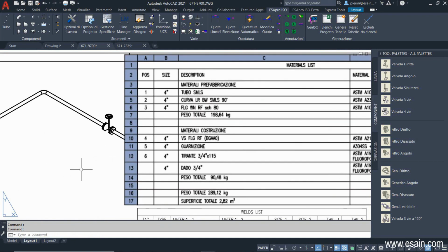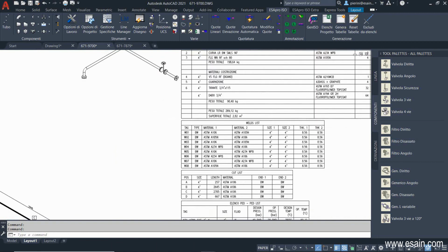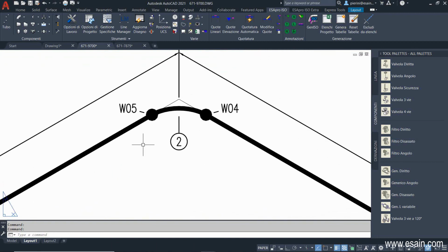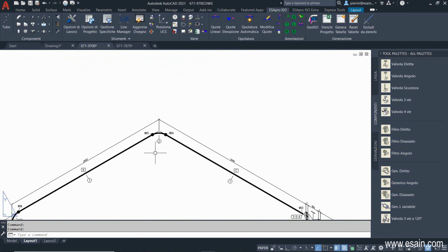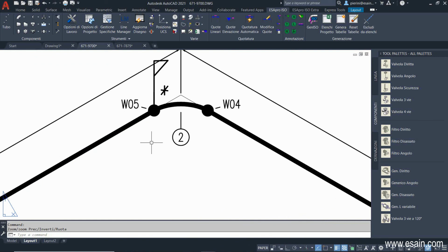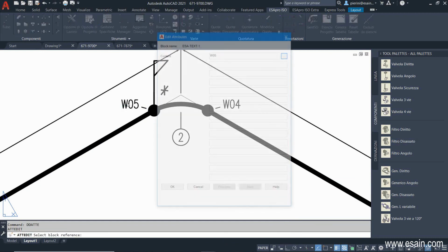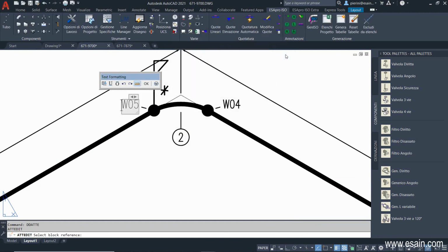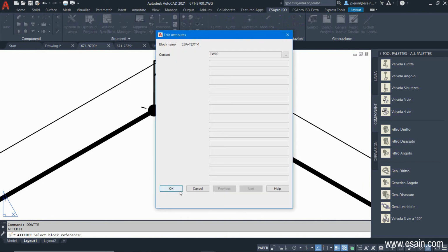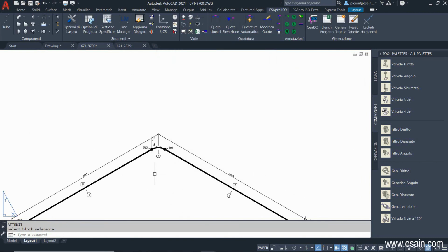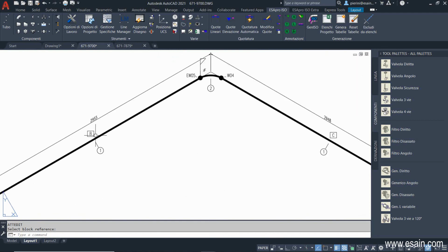This is a sketch for the line number 9700. Here we have a welding W5 that we want to make on site. Let's go to insert the spool limit symbol. It adds an extra length to our pipe. And rename the weld from W5 to EW5, Erection Weld 5. The welded pipe is B, and clearly this weld will require adjustment.